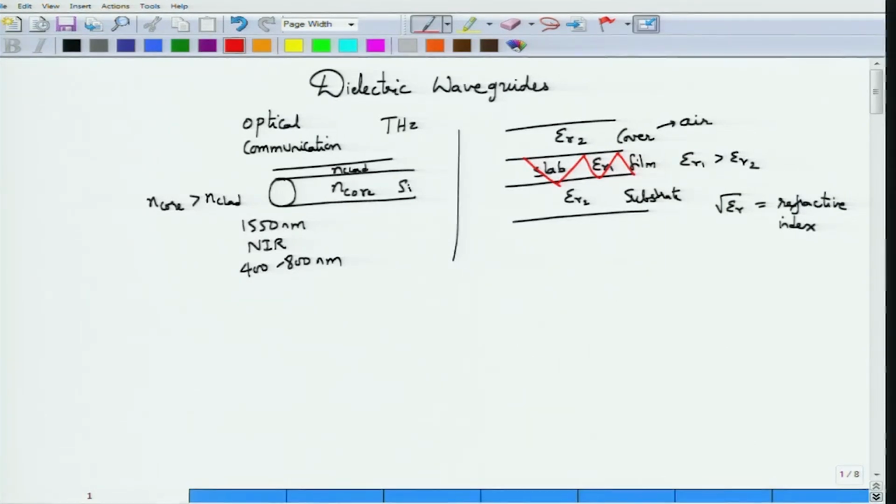Okay. So this is something that is interesting, right? If you compare this waveguide with that of a metallic waveguide, you had a nice metal hollow tube within which light or electromagnetic waves were being conducted. You could think of this conduction as a wave that is incident hitting the top plate or the top wall of the waveguide, getting reflected, getting again reflected from the bottom wall, getting reflected further and getting reflected, right?